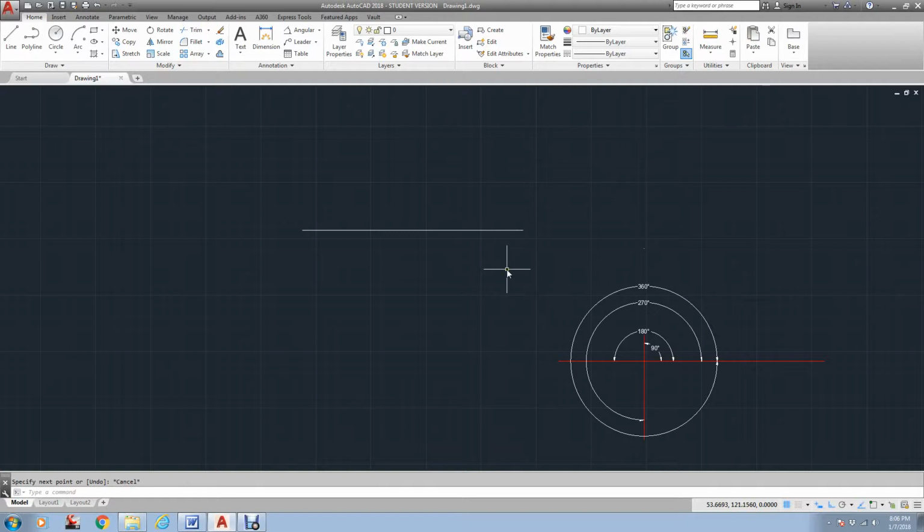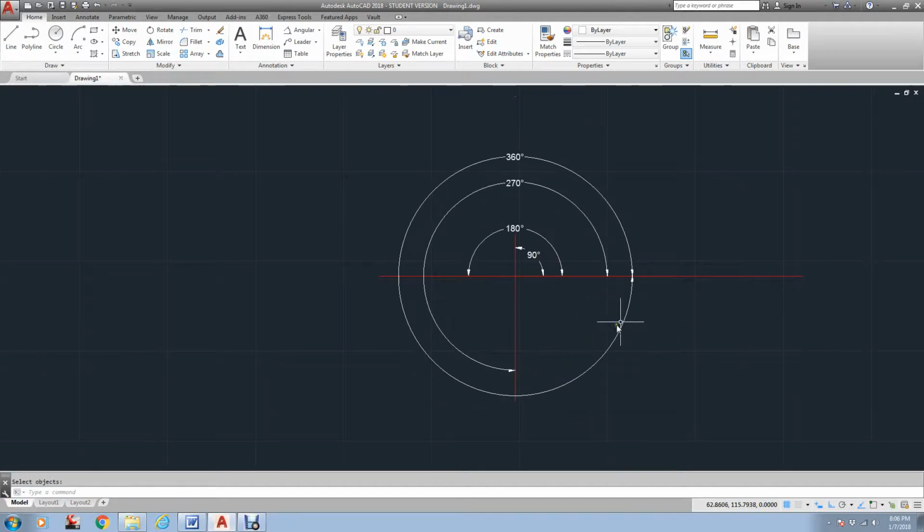Now, unfortunately, all our drawings, our lines are not all straight, so there is another option to use, which is the polar tracking, which I've got a little diagram here to show you how AutoCAD works. I think I went over this in another video, but just to refresh your memory, this is your zero line right here, your X and Y, but going to the left is positive.